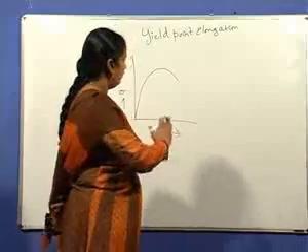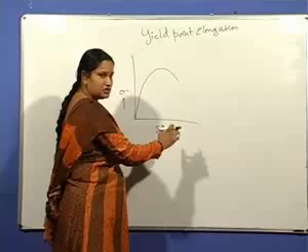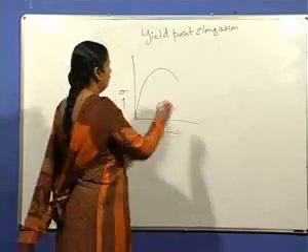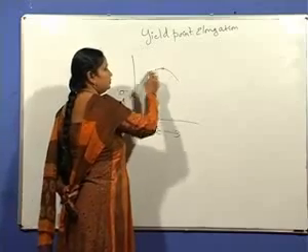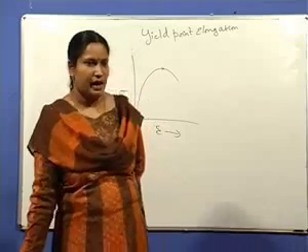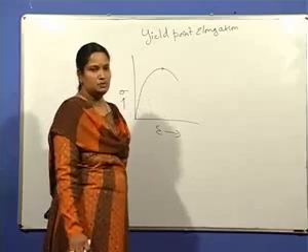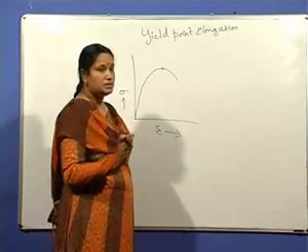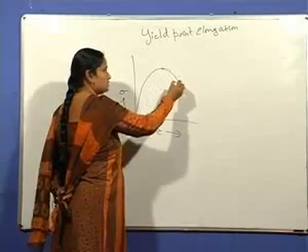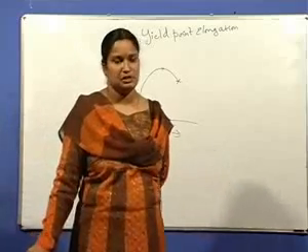Then the material undergoes strain hardening, increase in stress to cause further strain due to the previous plastic deformation. Then the ultimate load the material can withstand before fracture, and the onset of necking, that is localized plastic deformation that takes place at the point of maximum load, known as ultimate tensile strength, and then the load drops and finally results in failure, fracture of the specimen.